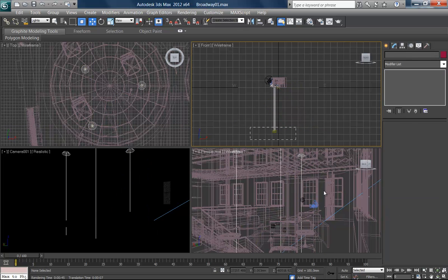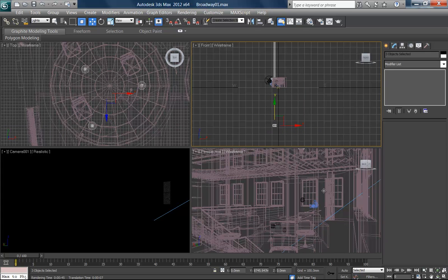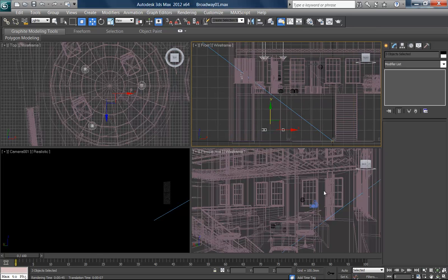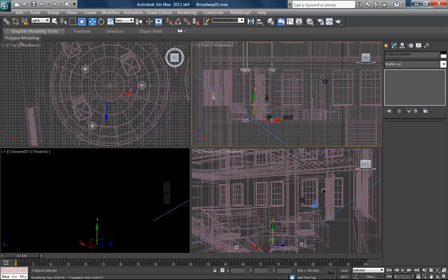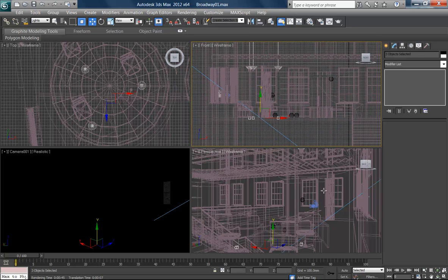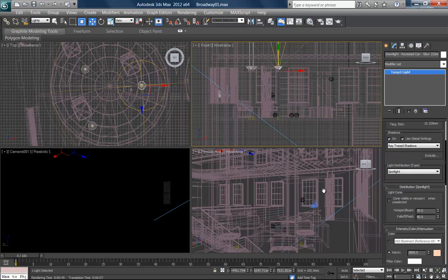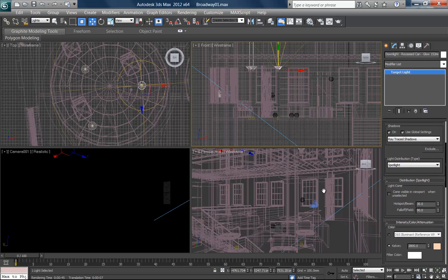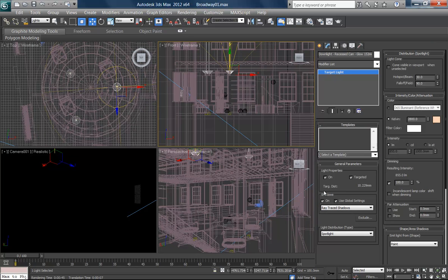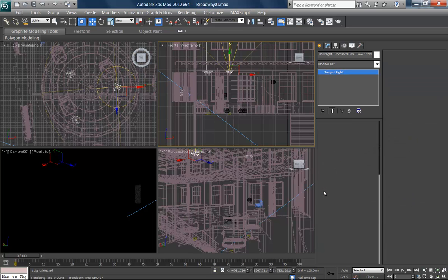You can see I've made a window around all the light targets, and I'm going to drag them up so that they're closer to the ground. Now, that's actually gone and done something really strange. It's pointing them up. Don't worry about that. It's because of the settings here. So I'm just going to go through that. When you bring imported lights in from Revit, they have a lot of things set up that you need to sometimes clear. So that's fine. We'll turn off the shadows option there.